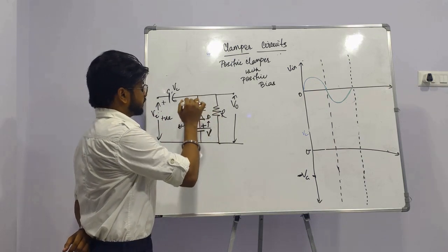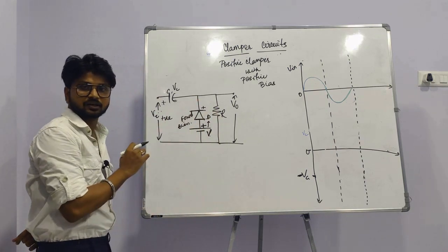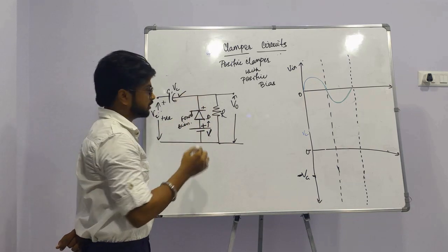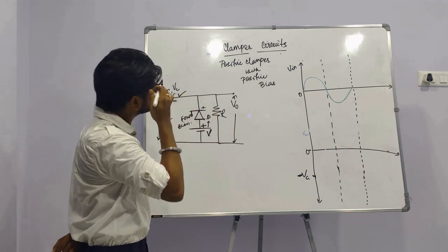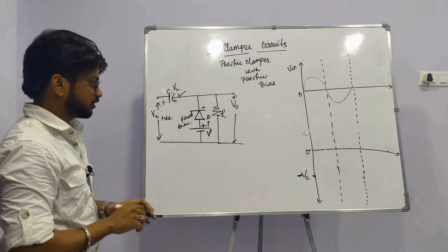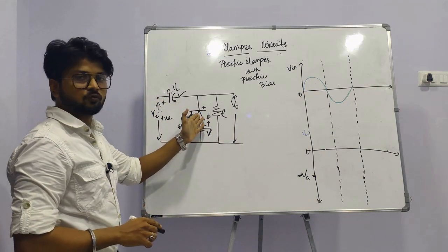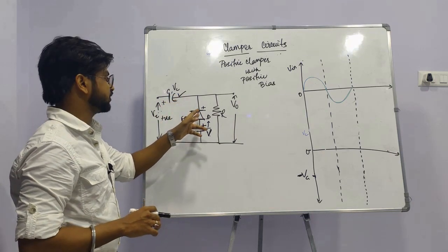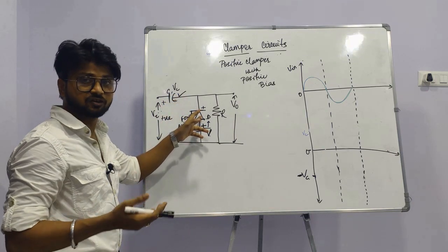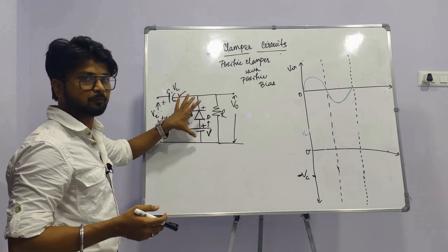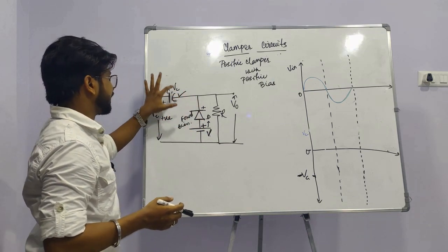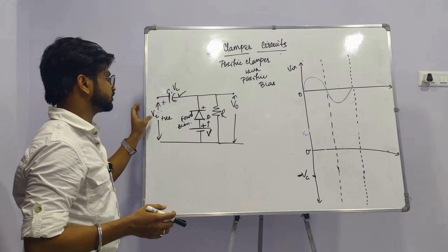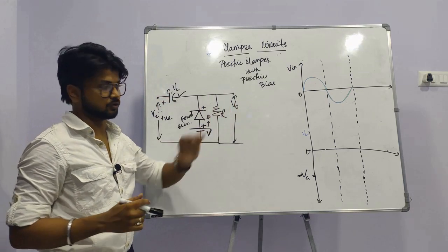In this condition, the capacitor gets charged in the negative half cycle and gets discharged in the positive half cycle. That is, when the diode is forward biased the capacitor is charged, and when the diode is reverse biased it behaves as an open circuit, and along with the capacitor's voltage Vc, the Vi voltage comes across the V0.